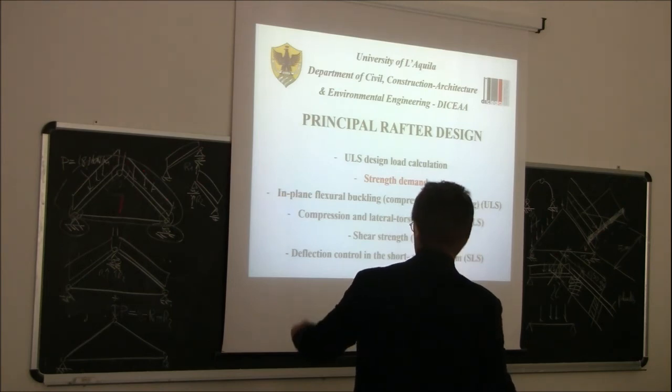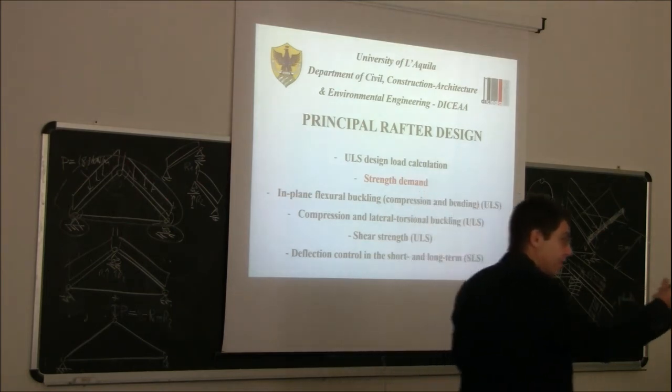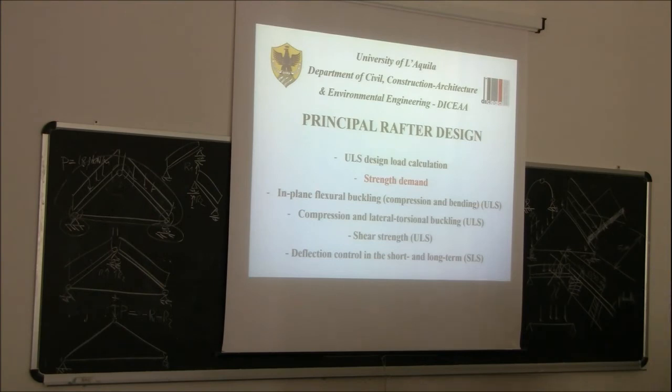But when you do a cross section here, do you know the horizontal component? No. So you need to write an auxiliary equation to find out this component. Here instead I don't write any auxiliary equation. That was the reason why. Of course, if you use some software, you don't need to do anything. Just put in your structure, and the software will solve everything for you. But you have to do it by hand. I found it easier to do it this way.